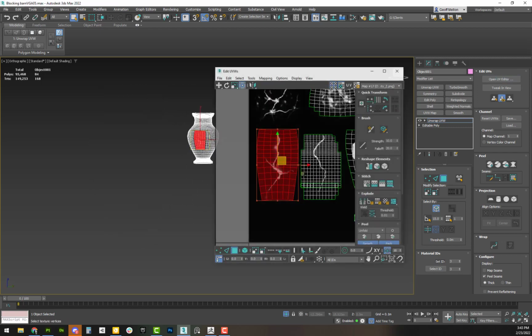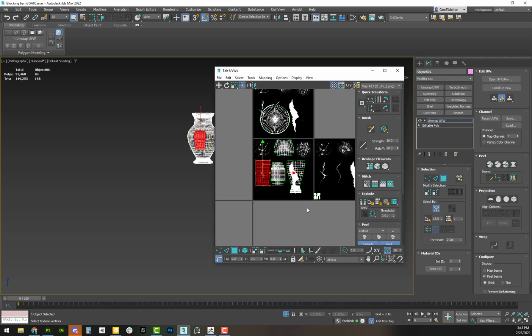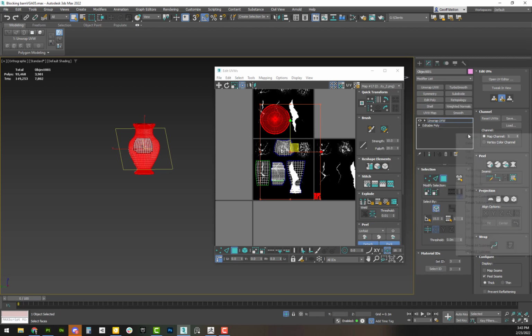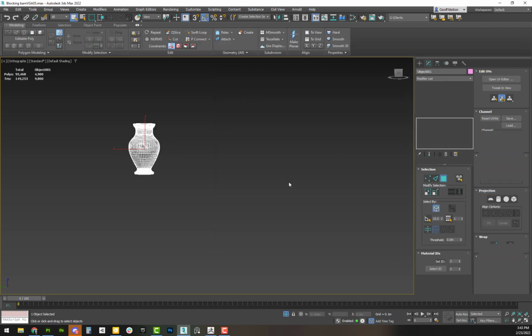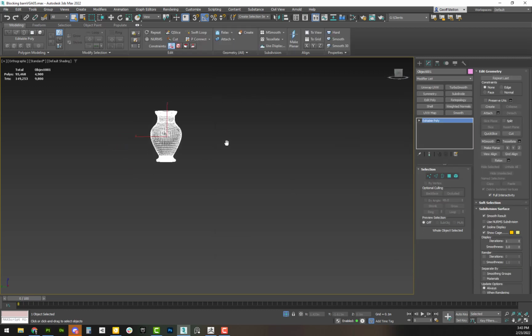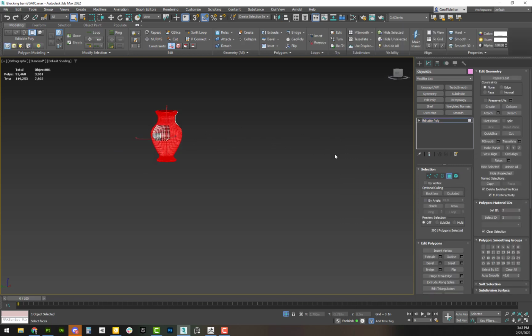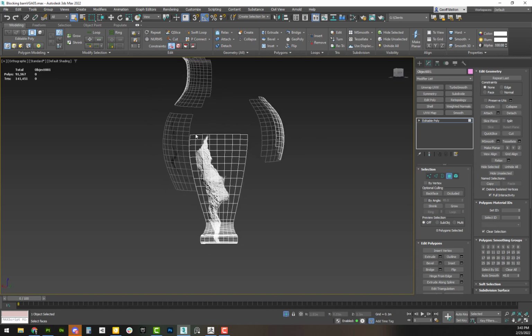If we want to start with, come back into Open Editor, sorry, one more thing, grab everything that we have the textures on, and then Control I to invert the selection, and then collapse it down to an editable poly, or you could collapse it in here, it's the same diff. But now when I go to polygon mode, it's going to select everything but what I just had, so I can just delete everything else. And then I can come back in here and clean this up.